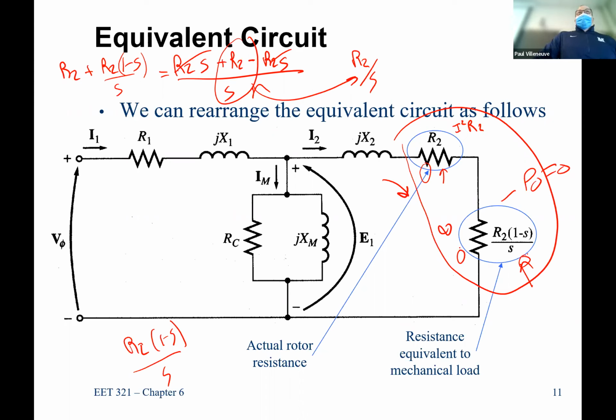So under blocked rotor conditions, you have lots of current flow and lots of heating in your rotor. You can't expect your rotor to last very long because your I squared R is going to be pretty brutal.